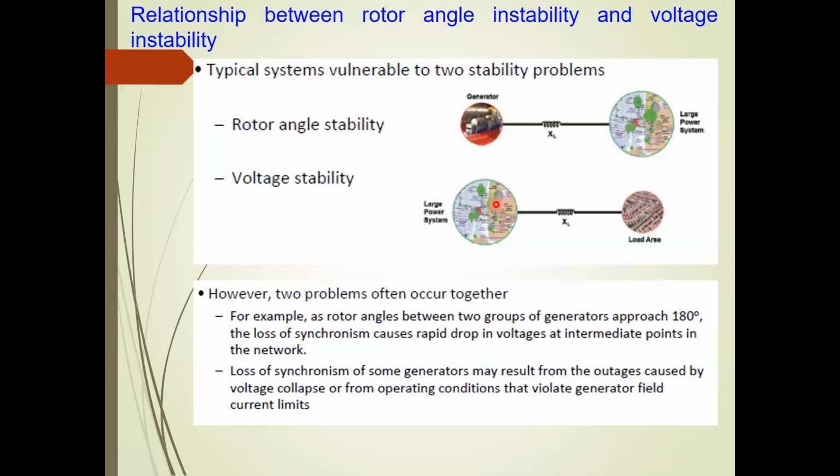Now, with this stressed operating condition of your network, if there is some maloperation or some disturbance, it becomes very difficult to control. And that is more important for us. If you are able to control, to regulate your generators and your system operation for those contingency-level events and disturbances, fine, but there is no margin, because it is already stressed. Yes, you're right, it is very difficult in those situations to regulate our network and our generators, and that results in tripping of the generators or the lines, and then cascading outage.